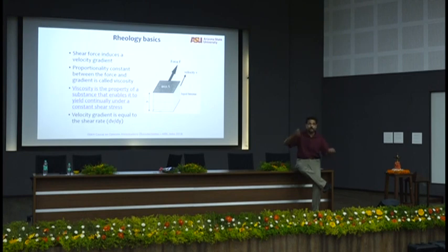So even in steel, you call it plastic flow. Some of the atoms have moved away from their initial lattice positions, never to come back to those positions again. You have plastic flow, so the material has yielded under that stress.